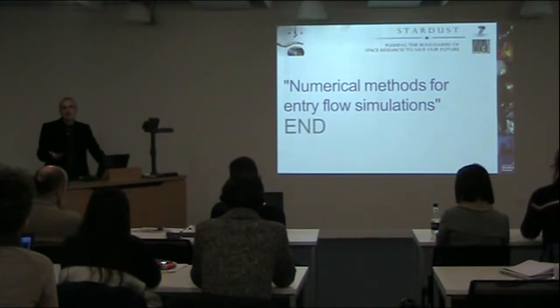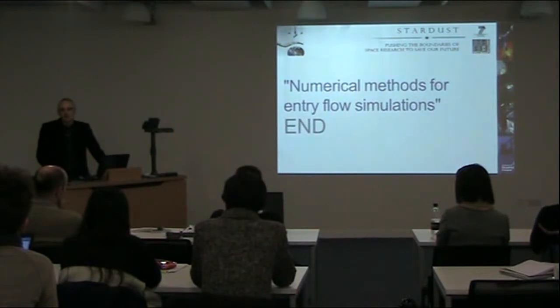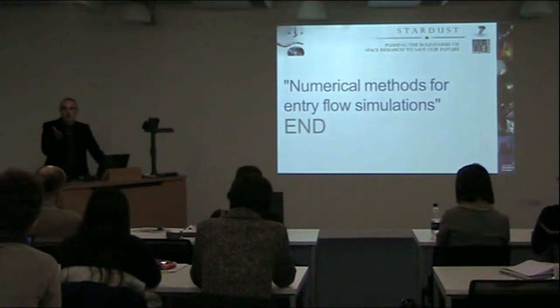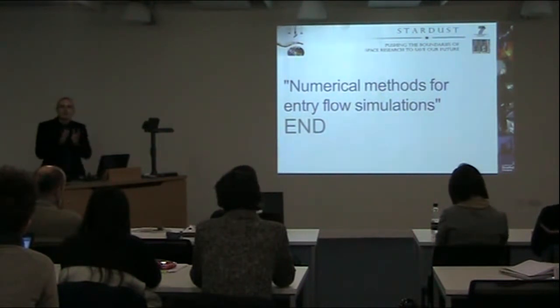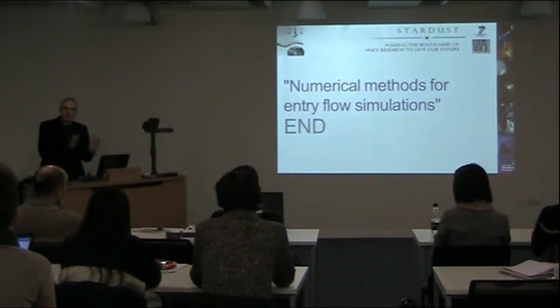Unstructured meshes are used because there are methods that can build them easily on any kind of complex shape. For structured meshes, you cannot have one single mesh. You have what is called the multi-block approach, and especially if there is a very complex shape, you sometimes cannot have total connection between the blocks, so you have, for example, a different number of nodes from one block to the other.